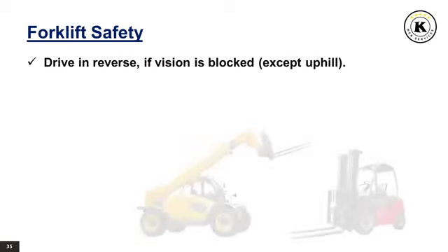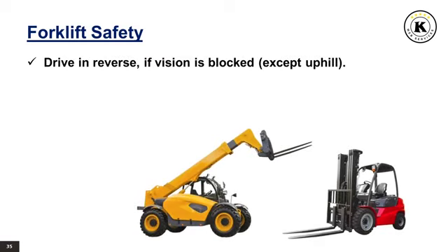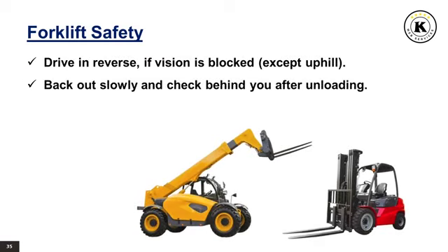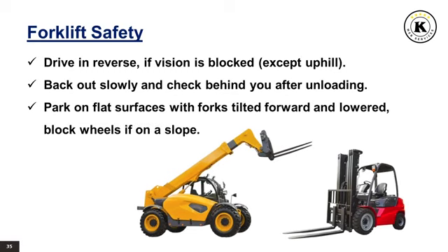Drive in reverse if vision is blocked, except uphill. Back out slowly and check behind you after unloading. Park on flat surfaces with forks tilted forward and lowered, and block wheels if on a slope.